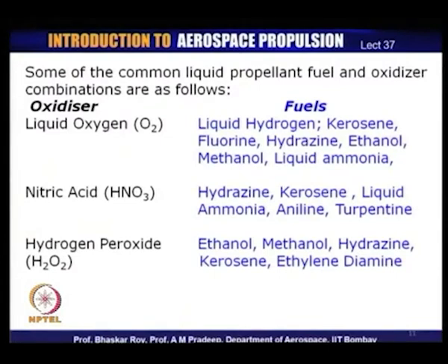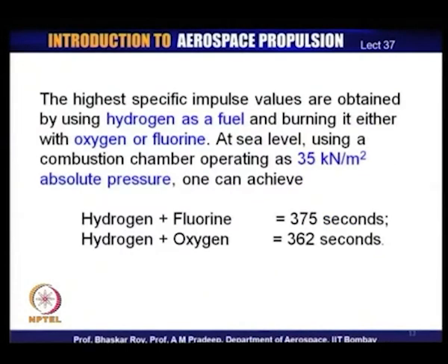of them may have a certain amount of toxicity involved, and hence they may be somewhat prohibited or objected to for use due to atmospheric pollution, but some of them do have very good performance indexes. Let us look at one or two of them in terms of how they actually perform. The highest specific impulse values are indeed obtained with hydrogen as fuel and burning it either with oxygen or